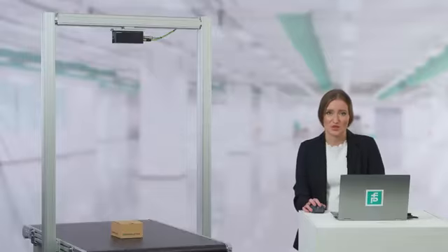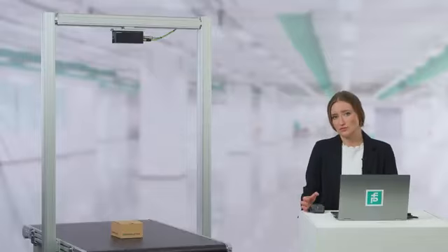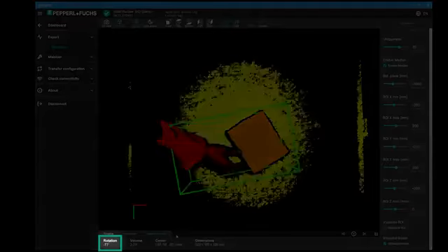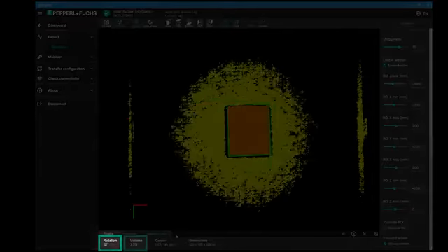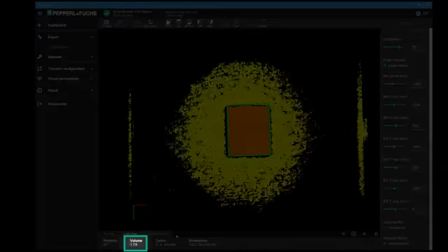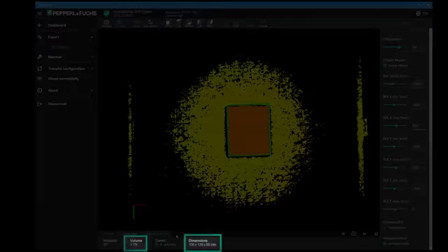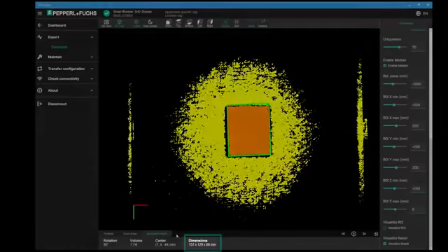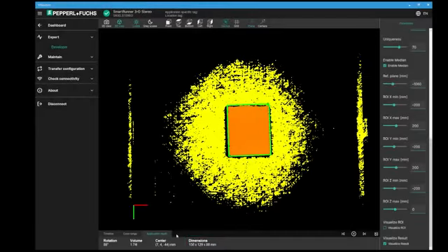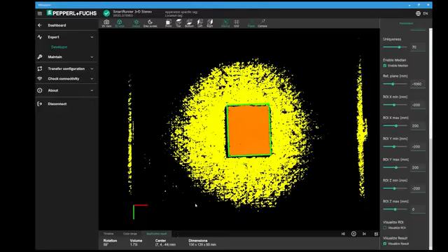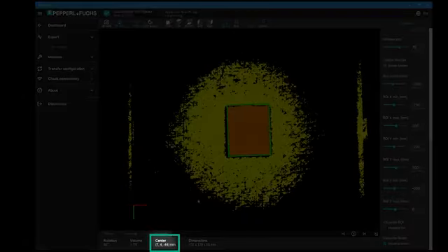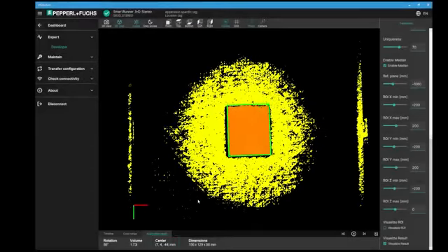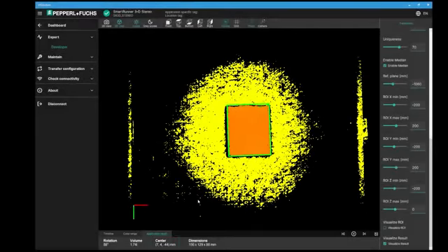The first result is the rotation. The rotation refers to the x-axis of the longer side of the object. We can also output the volume, length, width, and height of the object. The first value in the dimensions is always the longer side. The fourth result is called center, or also position. It outputs the position of the object relative to the reference plane, and we output the coordinates there.